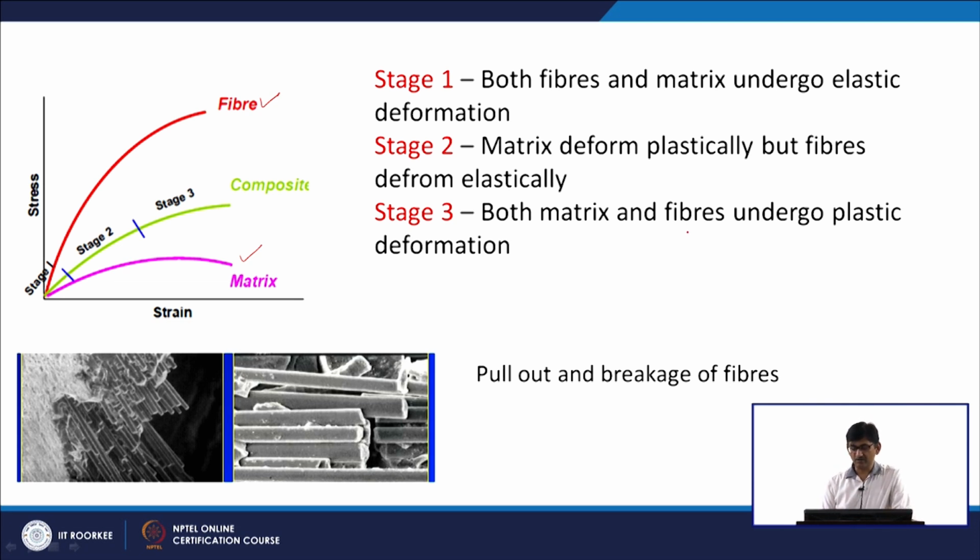So, if the fiber does not exhibit any plastic deformation, for example the fiber is made of ceramics, just for an example, and it does not show any plastic deformation, then throughout the deformation of the composite, the fiber will show only the elastic deformation, okay, whereas the matrix is showing the plastic deformation, okay. And we know that it will show the elastic deformation and then it will break, okay, though the matrix will keep on deforming plastically, okay.